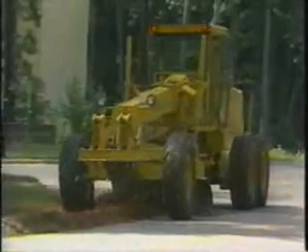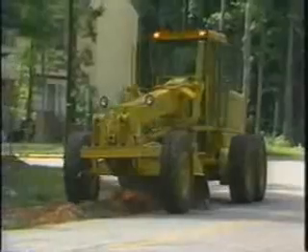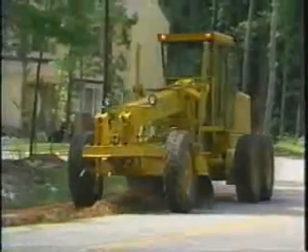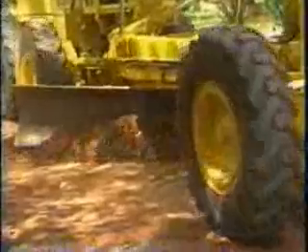On the second pass, pick up the windrowed material and spread it back across the shoulder. Again, a 45-degree angle is used for the blade. The toe of the blade rests at the edge of the pavement. The heel is at the edge of the shoulder. Set the blade height at the desired slope for the shoulder, typically 3/4 inch per foot. The heel of the blade is loose, so that material will be spread at the shoulder evenly and not create another windrow.